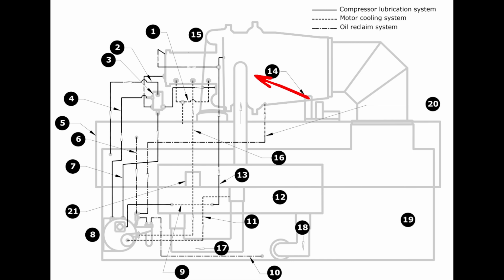Either way, what has happened is when that 515 hardens and makes it back into the oil sump, that little piece of hardened 515 will make it up into our oil pump, and it'll lock that gear pump up so it just can't rotate at that point. The only way to fix it is to pull this sump assembly out and open the pump up and see if it has any debris in there.